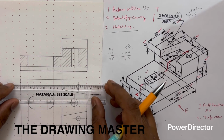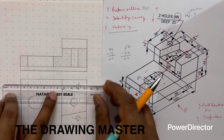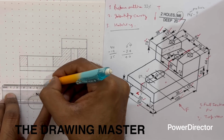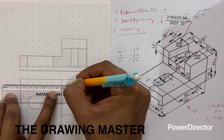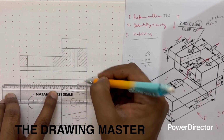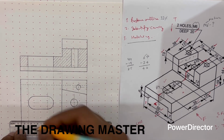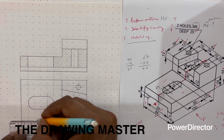So here we can draw the hidden line. For a hidden line we have to use the dash type of line. This is the hidden edge of the object. This is the cavity inside this base, 50 mm, which is not visible from the top. So that's why we are using the hidden line here.